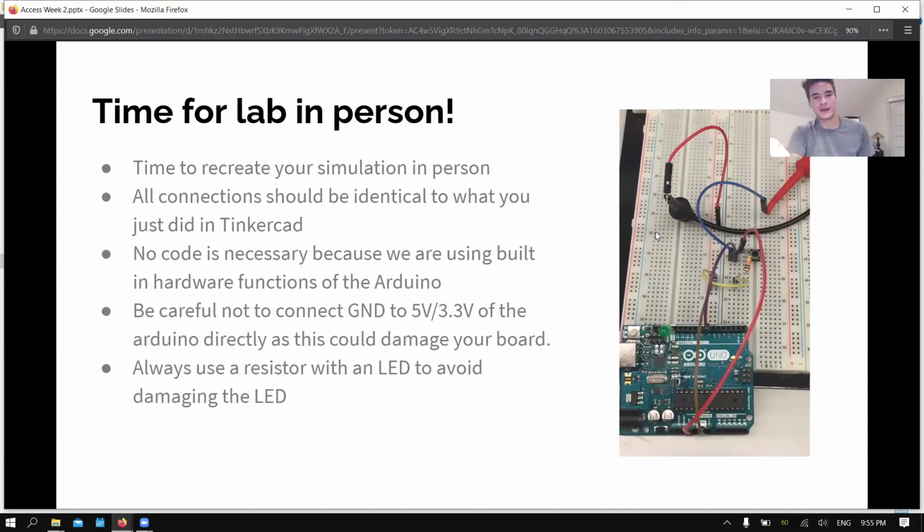Okay, so I'm going to build it now. So again, we need a breadboard. We need 4 wires. I'm using 2 reds and 2 black wires, and a resistor and a push button. So first, I'm going to build the board components, and then I'll connect the wires to the Arduino. So I'm going to take the push button and plug it in to the breadboard, kind of crossing this central channel. And you can see it's done the same on this picture.